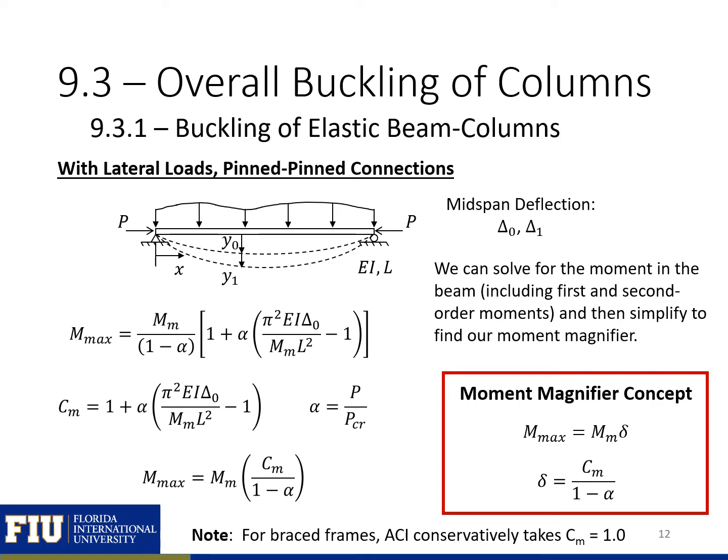We can next look at the case where we have a simply supported column with an axial load and a transverse load. So with this column, we'll have a deflection from our transverse load, our primary deflection of y0, and our magnified deflection of y0 plus y1.